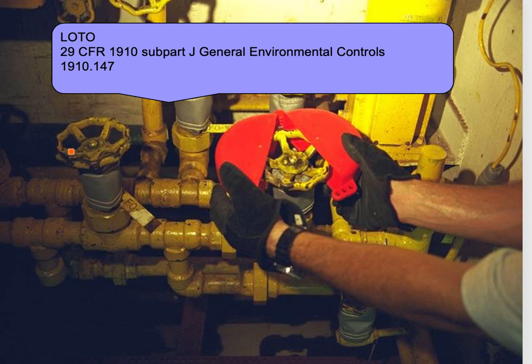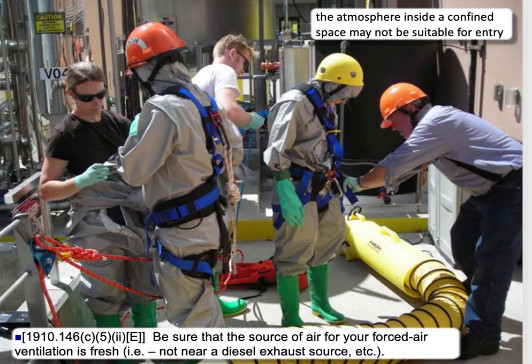So just a reminder, and we haven't covered it yet in this class, that lockout tagout is also important with confined space, and it's found in the same area. That's Subpart J, General Environmental Controls. The atmosphere of a confined space, you need to monitor for it. And one way that you can ensure that it isn't oxygen deficient is that you ventilate it before you go into the confined space, and you monitor while you're in there.